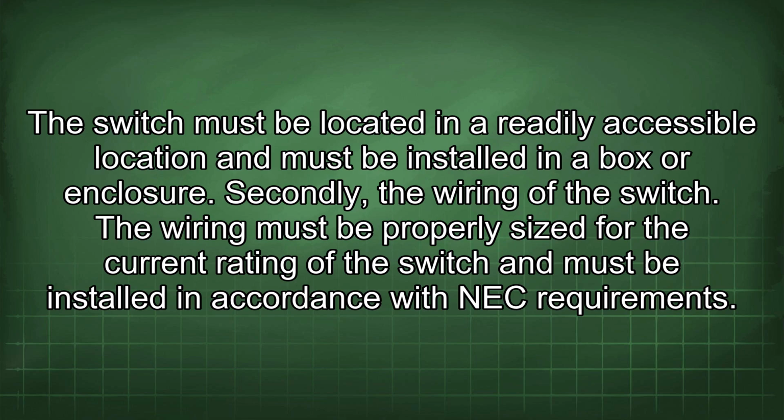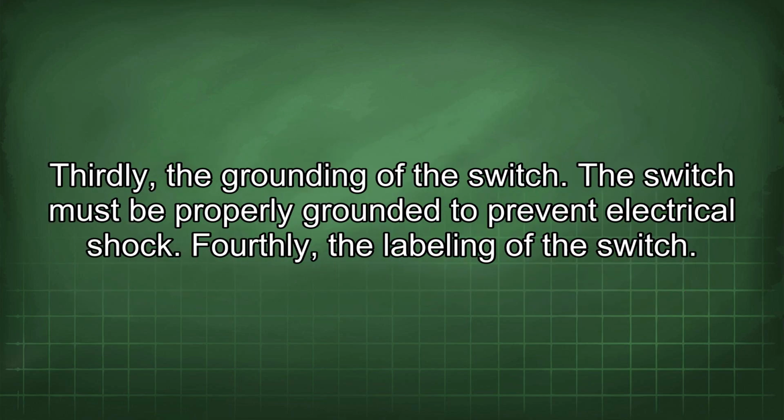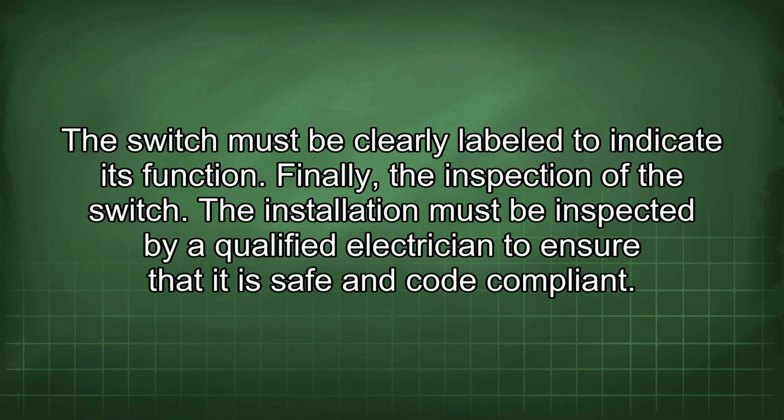Thirdly, the grounding of the switch. The switch must be properly grounded to prevent electrical shock. Fourthly, the labeling of the switch. The switch must be clearly labeled to indicate its function. Finally, the inspection of the switch. The installation must be inspected by a qualified electrician to ensure that it is safe and code compliant.